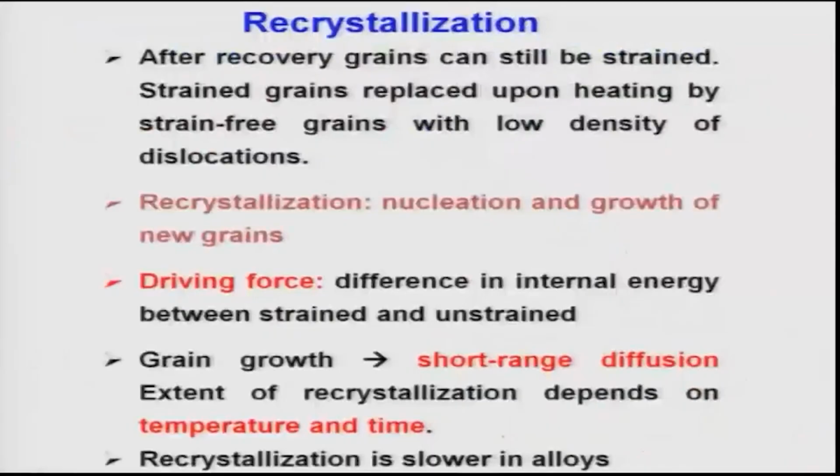Now what can happen in the next step? The next step is, as we increase the annealing temperature to higher than that used for recovery, we will have a new kind of phenomenon known as recrystallization. As the term suggests, it is basically crystallization again.